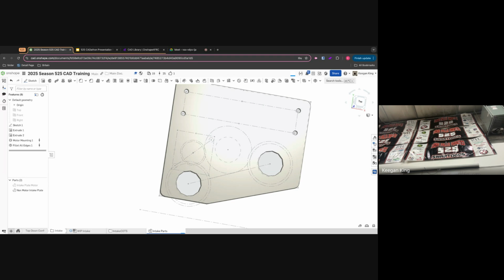You can make a new part studio for every part, and then you just essentially get the same studio. Go to your insert. Yes, double click on it. Essentially it's a project file. And if you want to get something from outside of this file, you have to use derive to extract it from another part studio outside of it.